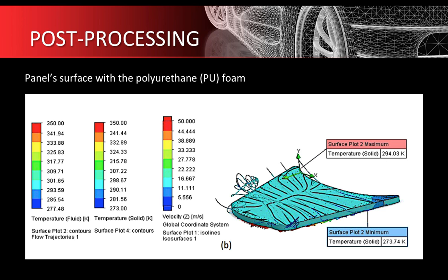This has significantly influenced the temperature distribution at the interface between the outer face of the hood panel and the PU film. Therefore, the heat on the surface above the panel at point T2 is transferred slowly across the PU film to the outer surface of the PU film. Moreover, heat transferred by means of forced convection is also considered in both of these simulation analyses.